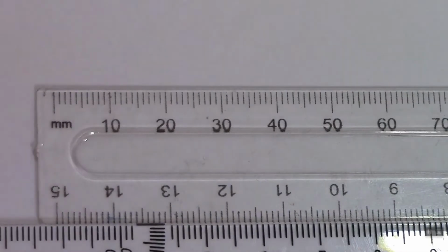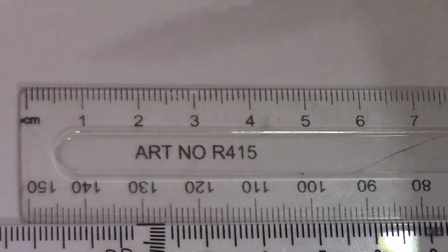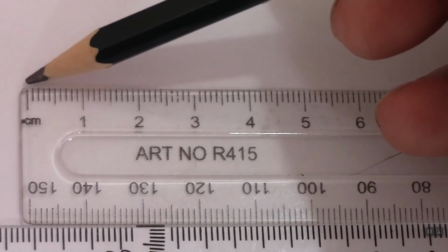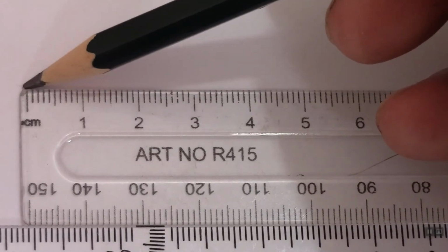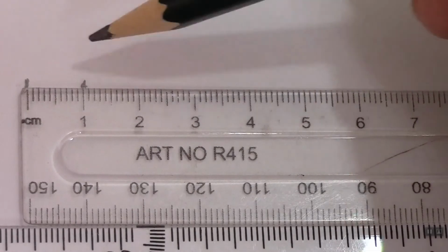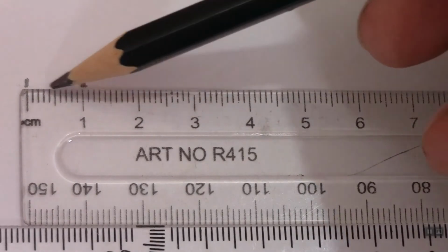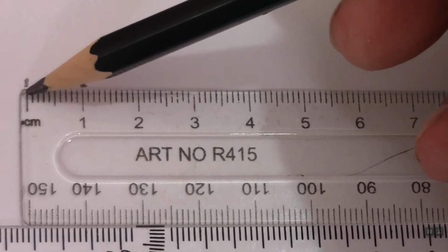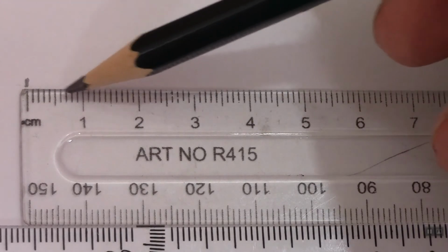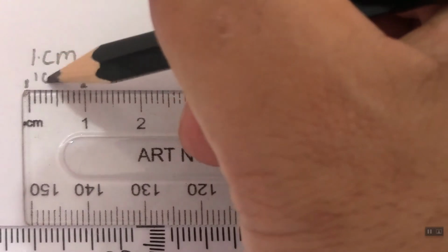So how do we draw lines accurately? Some rulers only have centimeters as readings, but it doesn't matter. Make sure that, as you have seen previously, the zero starts here, not from the edge here. Make sure that you start from the 0 line. From 0 here to 1, there is 1 centimeter. Between 0 and 1 you have small divisions, which are millimeters. From here you have 1, 2, 3, 4, 5 divisions, that makes 5 millimeters, and another 5 millimeters here, which makes 10 millimeters. So in 1 centimeter you have 10 millimeters.